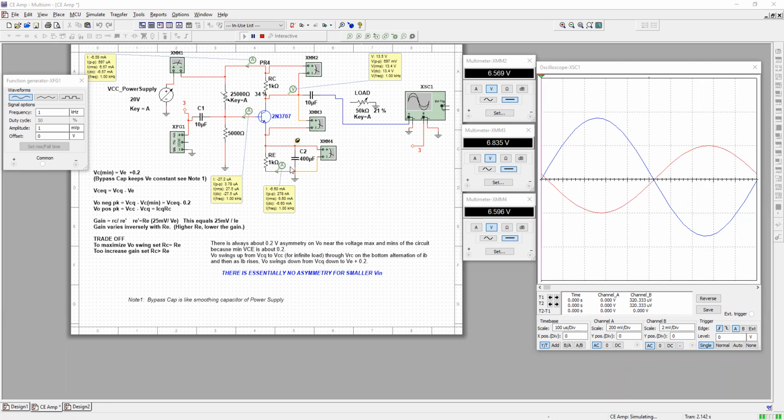And the input stage also had a smoothing capacitor that allowed any fluctuations in the input to be smoothed out. The capacitor would basically discharge if the voltage dropped, and it would keep the voltage that it's feeding on the right side of the circuit, or for the load, constant.